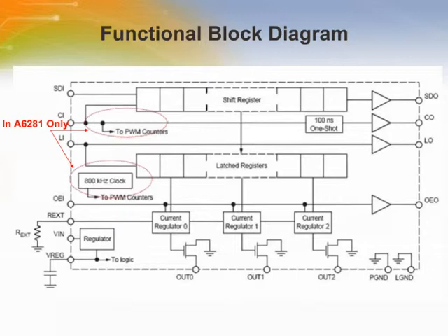The LED drivers also have a built-in linear regulator that eliminates the need for a chip supply bus and external voltage regulators. The driver is designed to allow daisy chaining many drivers together. Internal output buffers allow data signals to travel long distances through strings of LED drivers without needing extra driving hardware.